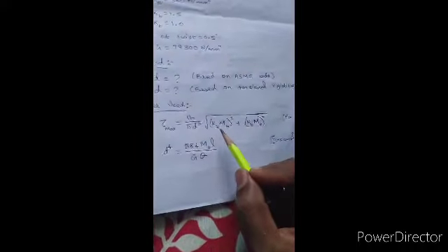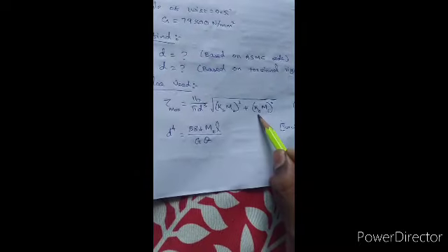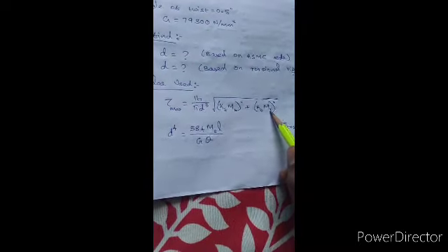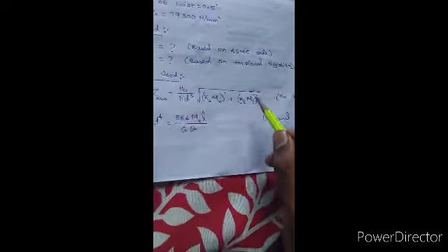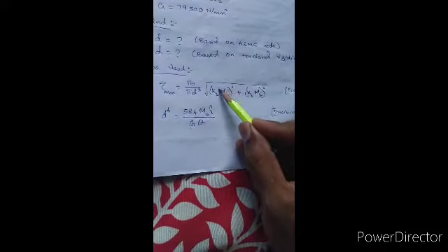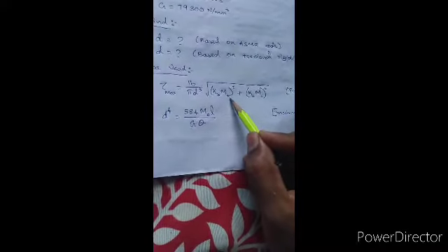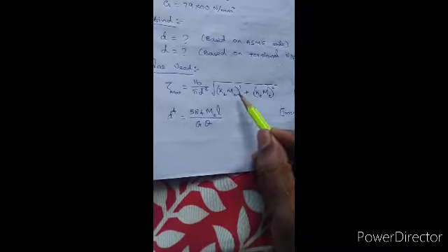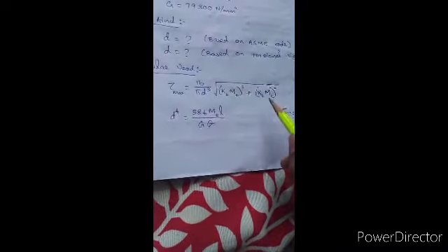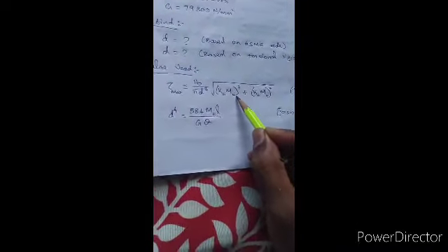To use the ASME method, I am telling you again. Now we have the tau max value, KB value, KT value given in the question, and the MT value we just got. Still we have to find the MB value, that is the bending moment value. This is the crucial thing in this problem, finding out the MB value. MB means bending moment.